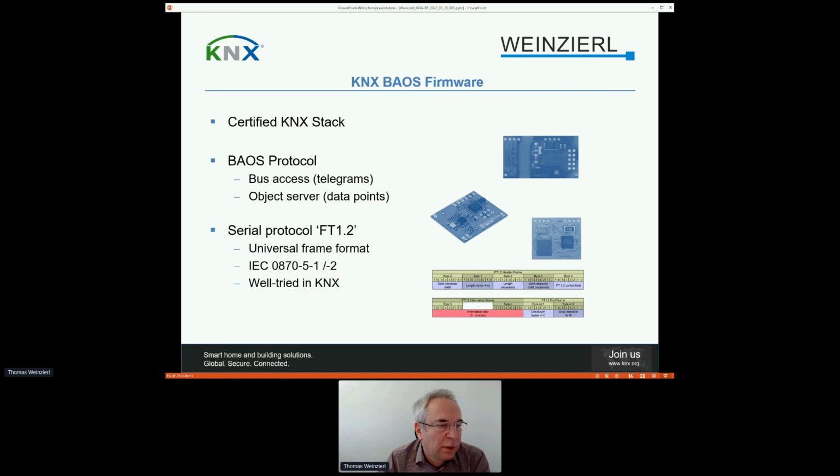And for serial modules, all these telegrams are embedded in the FT1.2 frame format, which is a universal frame format already used in KNX in another context. It has not been invented by KNX. It's an IEC standard, and it was well tried, for example, in former BCUs for KNX.